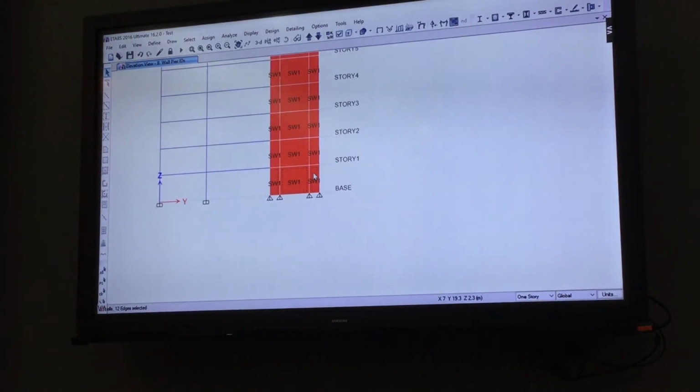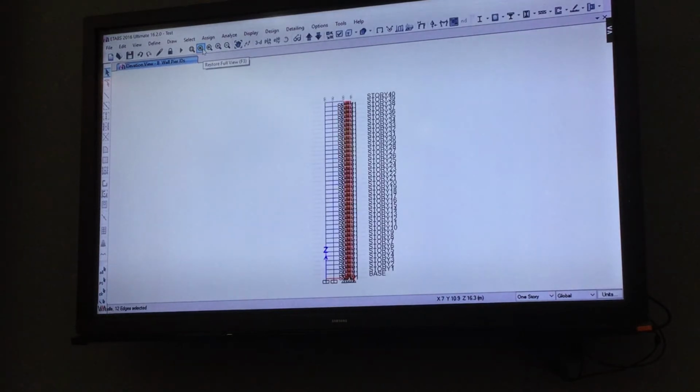In your term project, you use the uniform pier section, which just provides uniform reinforcement, and let the program design the vertical reinforcement. But for the shear design, I want you to design manually, at least 2 locations, whatever you like.